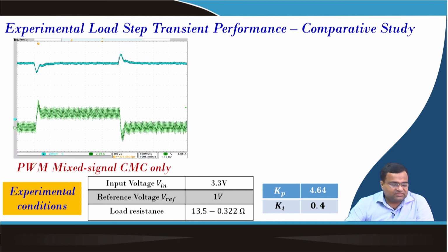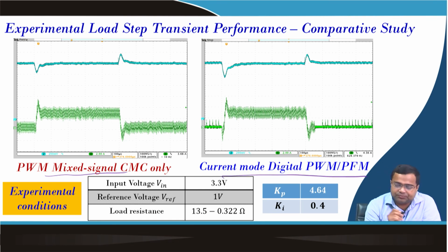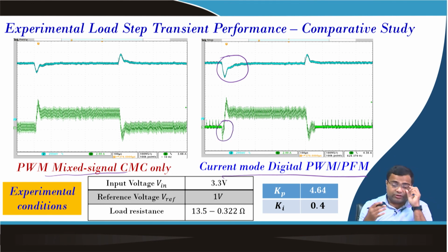Okay. And this is the transient performance comparison. This is throughout PWM, and this is multi-mode control. So, there will be a reduction because of this negative error at the time of transition when we are making the integral reset, but there are research papers and commercial products which try to improve this mode transition. This penalty is due to the mode transition when you are doing the integral reset. So, there are n number of techniques to detect transients and take action by adding a nonlinear term. So, we are not going to discuss that here. This may be a research topic, or the participant can do further exploration.